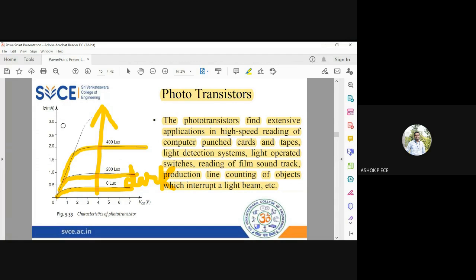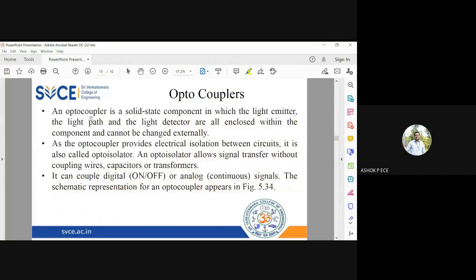That's why we said photodiode plus amplifier has to be used. But instead of a photodiode plus amplifier circuit, I have one phototransistor circuit that helps me do both purposes. It works based on light, and the current is also amplified to milliamperes, so that this phototransistor can drive other applications which work on light. Okay, that is the main thing you have to understand in phototransistors.